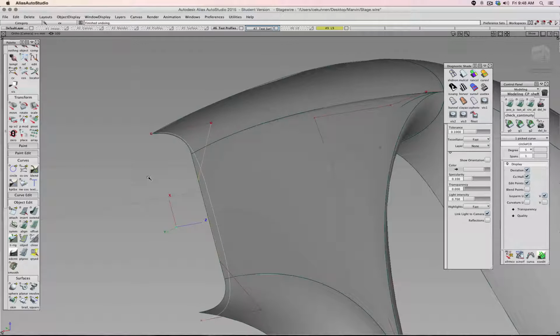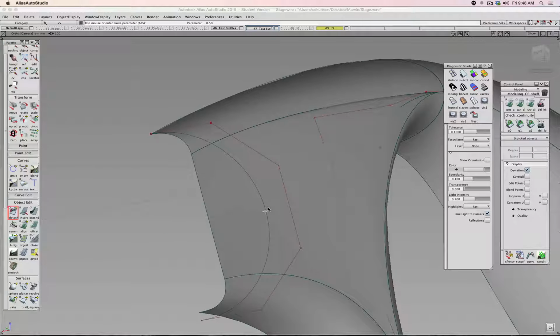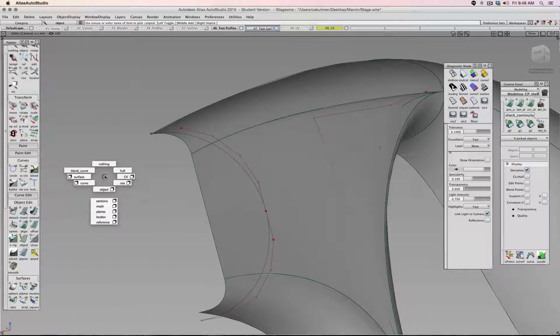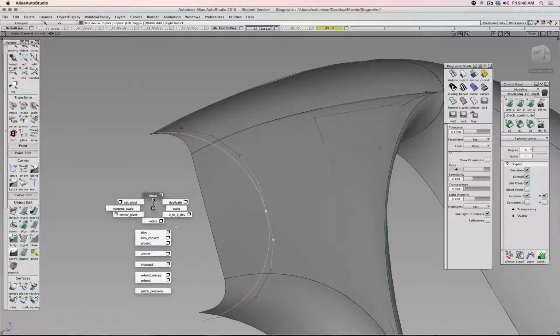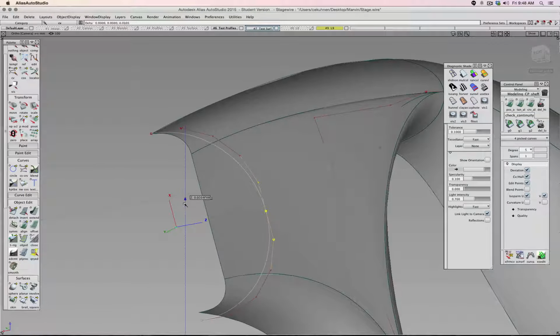Because one step before I did that, I went ahead and went to detach, alt click onto this curve. There's the midpoint, spacebar. You see now I have two arcs. And then, for example, I was able to select those CVs, move along the z-axis, select the next.